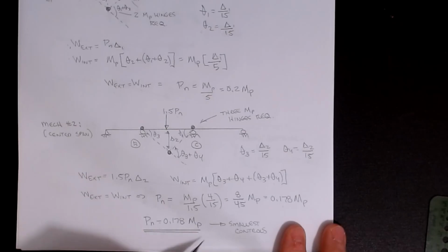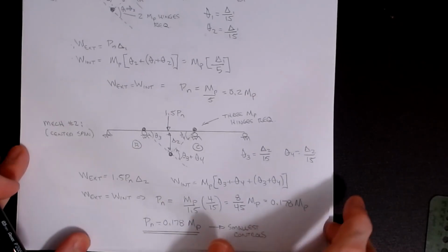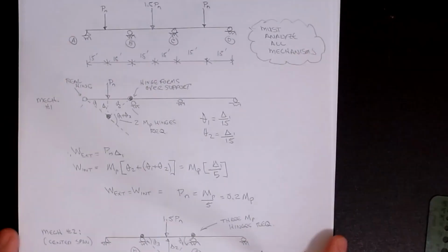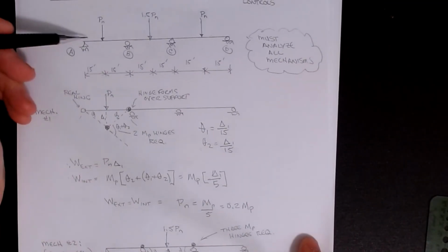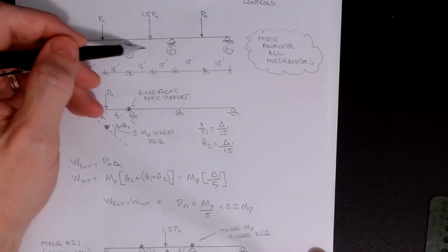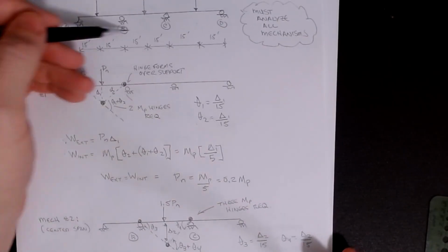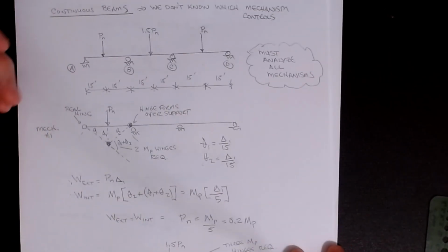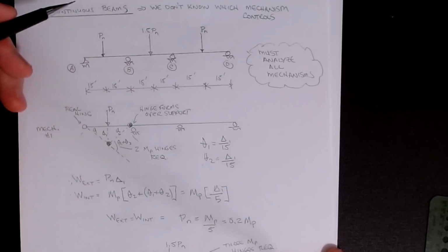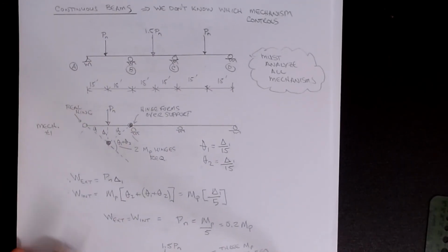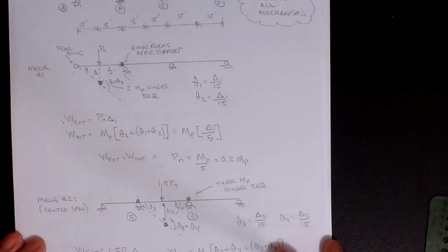And then I can take this formula and just like you did before, you can rearrange this and set it equal to ZxFy, and now you can solve for the required section modulus to hold this thing up. Now, the one thing that we did assume in all of this is that Zx was the same all the way through, that Mp was the same all the way through. If that's not the case, then you have to play with different Zxs, but again, you're just modifying these formulas and kind of playing the game that way. All right, so that's kind of how you can handle continuous beams.